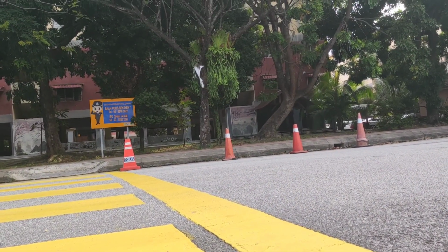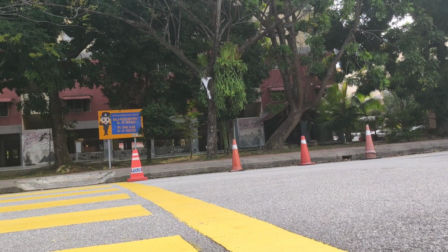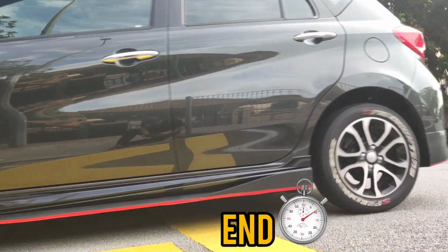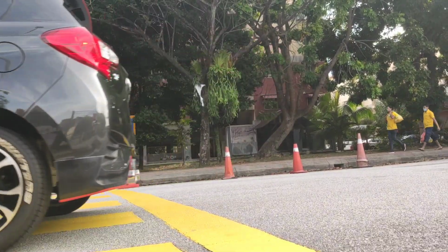As the front wheels of the target vehicle cross a mark at the starting point of the predetermined study length, the observer starts the stopwatch. The watch will stop when the vehicle front wheels pass a reference line or the ending point. The time taken was recorded in the form.